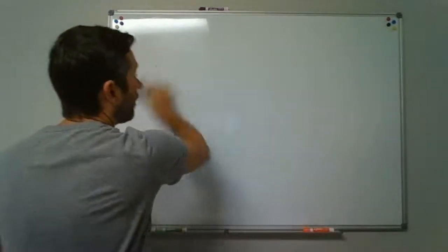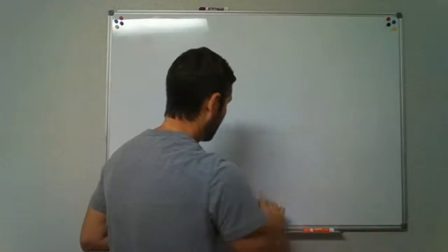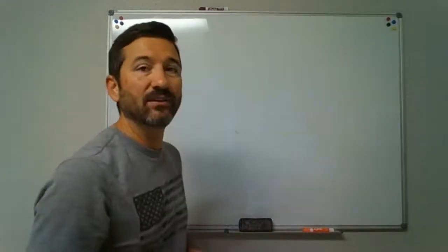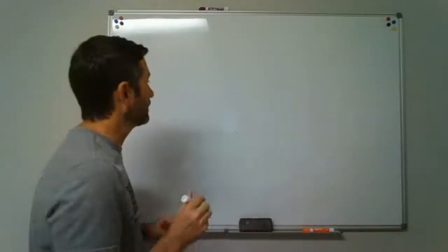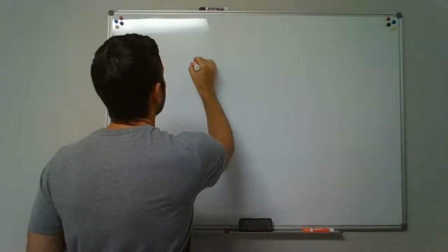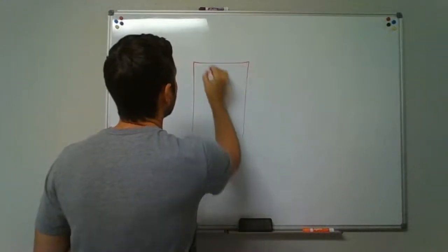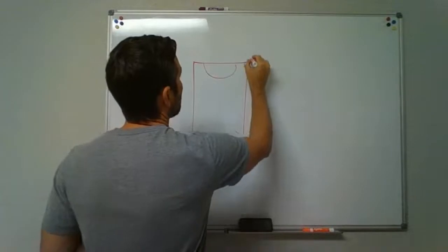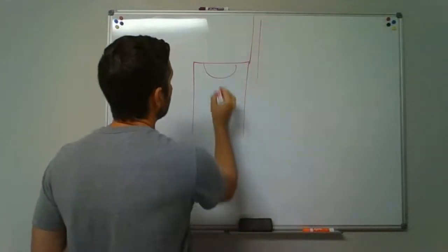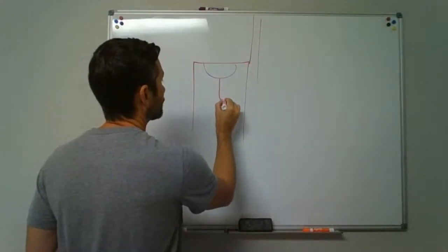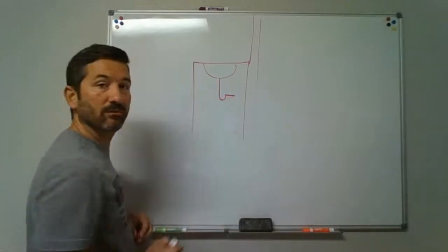Now, it says that all of your plumbing fixtures are allowed to be individual vents, so you can individually vent every fixture in the house. So let's look at maybe a lavatory sink here. There's the sink. Here's the back wall going up. So what you might do is you come down, there is your trap underneath the fixture.